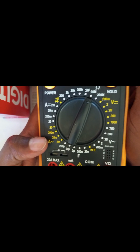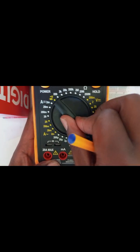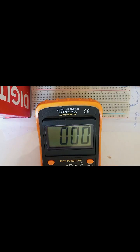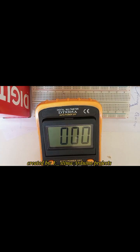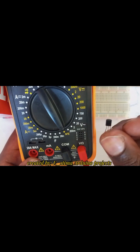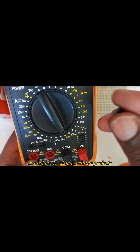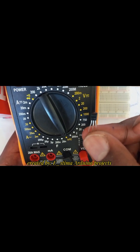Now, since we have identified the collector, we can measure the transistor current amplification gain, or HFE, and for that we are going to select HFE on our multimeter. We already know that this particular transistor is NPN. Where we have HFE, we have PNP and NPN. With my transistor facing me, I know that my first pin is the collector, my second pin is the base, and my third pin is my emitter.